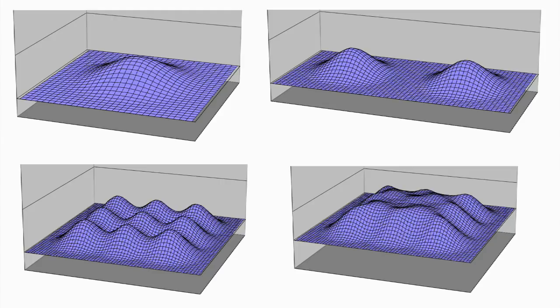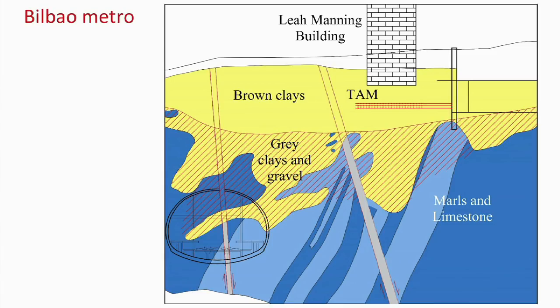And of course, what you have to do is check the reaction of the building and adjust your injection at the same time that you are looking at the response of the building. So you have to do that in real time. And this is the key component and the fundamental way of working of compensation grouting, because nobody actually believes that you can predict anything here.